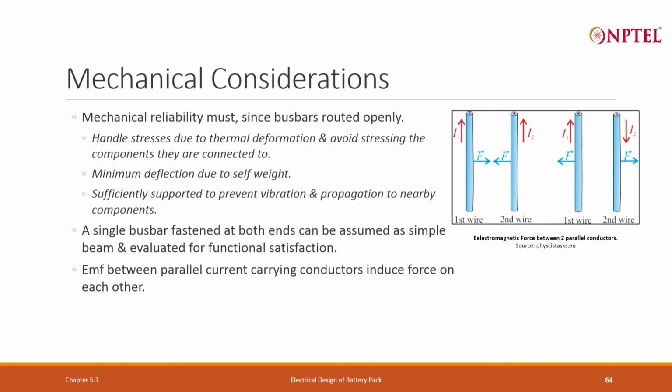It has to handle, because now you have limited the temperature rise to some 5 degrees, 10 degrees or 20 degrees. Within that, if any thermal stress develops, the bus bar material should be able to accommodate that thermal stress, meaning it should not fail.